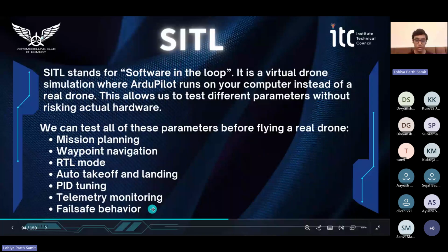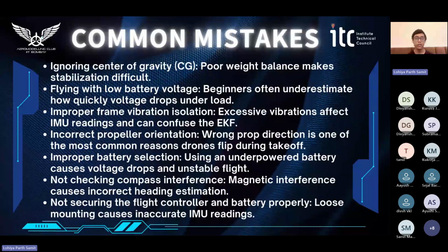So moving on to some common mistakes that beginners can make. Please pay attention to this slide as this is very important and something that you should keep in mind when designing your drones. So the first big mistake is ignoring the center of gravity, which leads to it being pendulum unstable, and the poor weight balance makes the stabilization difficult.